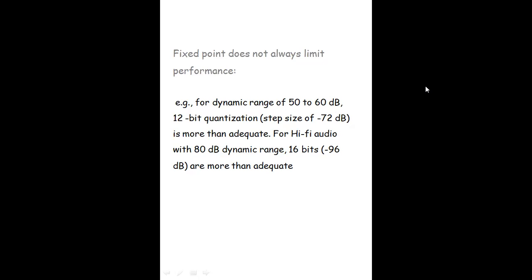How does the DSP processor differ from other processors? Actually, special purpose processors are designed with features required for DSP applications, such as multiplier and accumulator, modified bus structures, multiple access memory, multiport memory, and pipelining. The conventional microprocessor does not have these. The advantages of DSP processors are low power requirement, low cost, real-time input or output capability, and availability of on-chip memories.